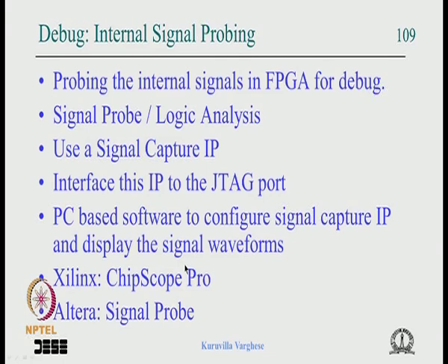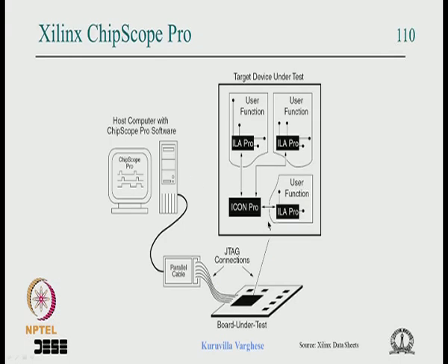The only thing is that this IP, this circuit, occupies some space within the FPGA. So if you are not floor planning the rest of the circuit, it can sometimes upset the timing performance of your design, but if you properly floor plan, that's not a very serious issue because it doesn't occupy much space.